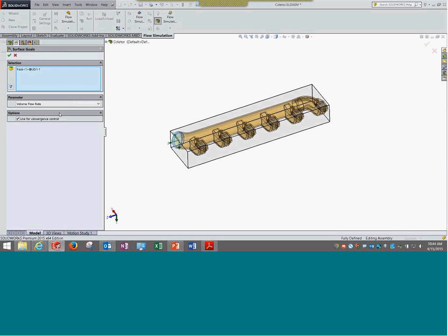There are different ways of discussing goals, but two important things I can put across are these. Irrespective of the goals that we specify, the software will try to converge on most of the global parameters. Number two, the goals are more relevant for you to control the way the solution is going. I want to ensure a certain output, in this case the velocities and volume flow rate at each of the outlets. I want to ensure they match and are consistent.